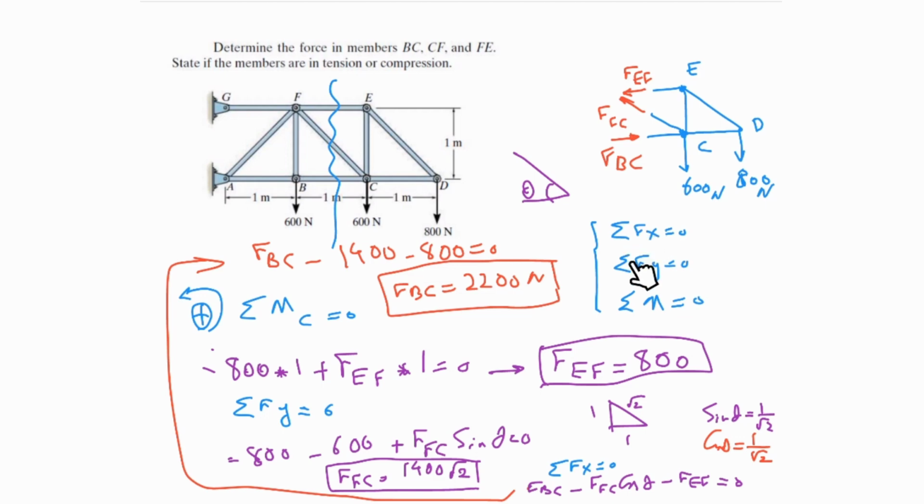We have three unknowns. It's important to start with the right point. It is possible to do these things all together and do the sigma around any arbitrary point, but you can start from the point that gives you one unknown for each equation. Find that and then go to the other ones and go step by step. As you can see in the last one, we have just one unknown.